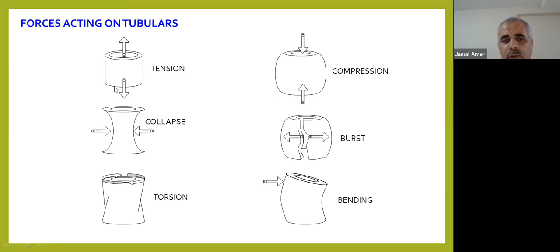Not only these, we also have other effects. Some we have corrosion. This corrosion could be enhanced by H2S or CO2. So when we have an H2S or CO2 environment, we have to select a different alloy that is fit to work in this environment.